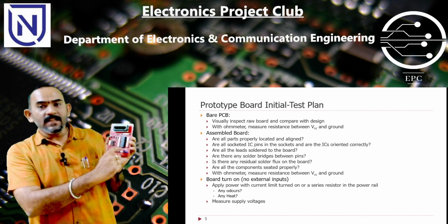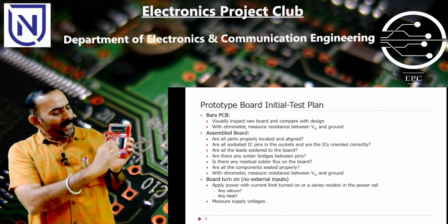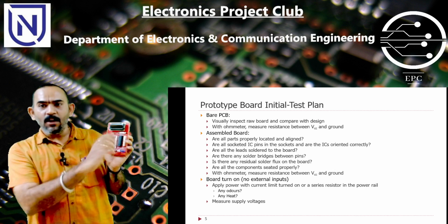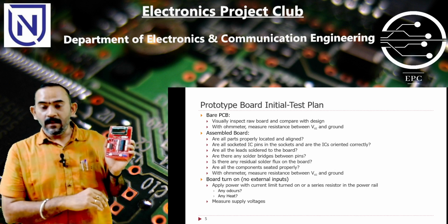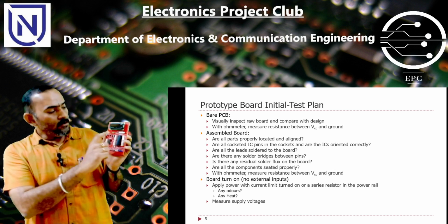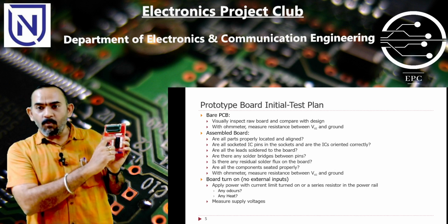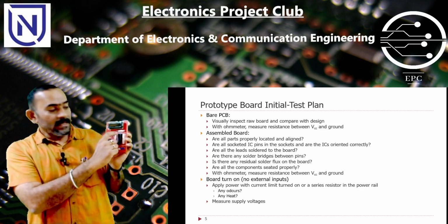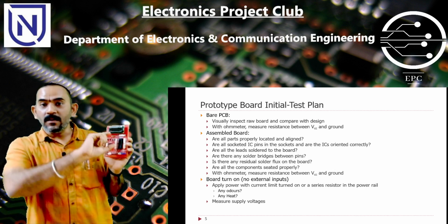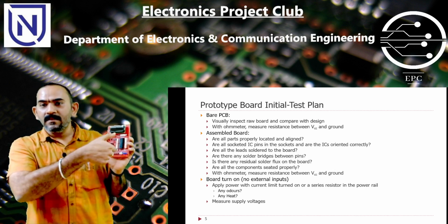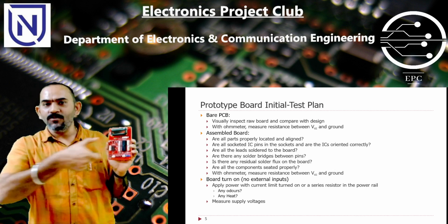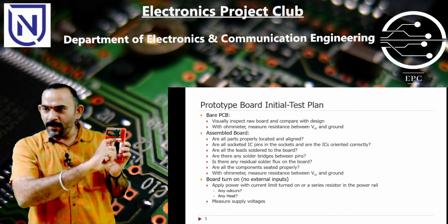Another one here. Now here I have put this component on an IC base. Assume that you have mounted or soldered this IC directly onto the board. That is also possible. Now you have to check whether pin number 1 of this IC is aligned to the proper hole given on the board. If it is not, you have put it in reverse. That is a problem. Your board will not work. The only solution is to remove the IC, turn it and put it back in.